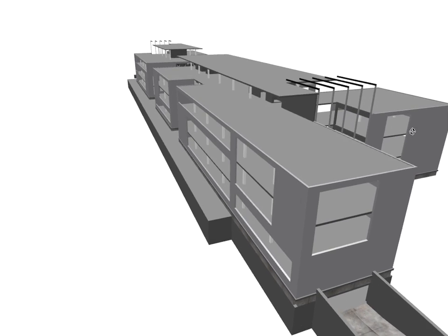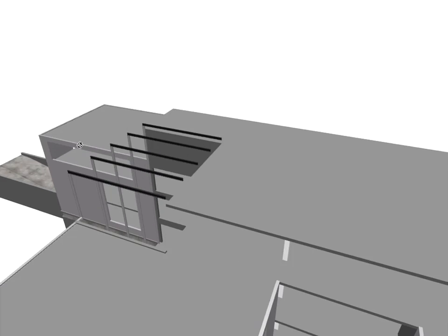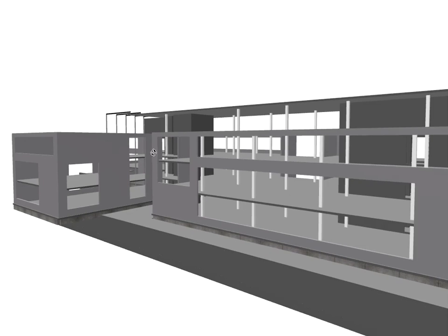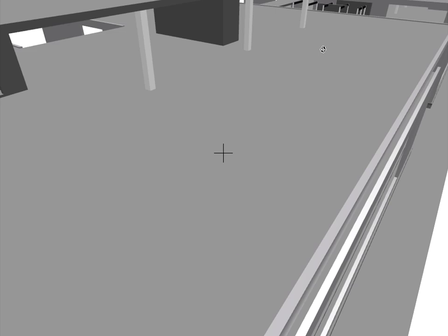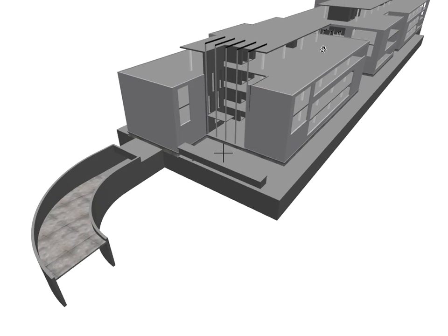As you can see, the IFC model has been converted perfectly and opened in ArchiCAD after the Revit Structure environment. You can compare the imported model with the original one. The structural engineer has changed the size of almost all of the concrete columns on the basement level. To save time, we'll use these 3D columns instead of modifying them in the original model.